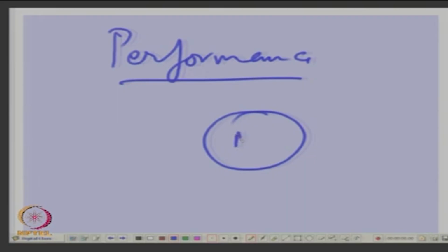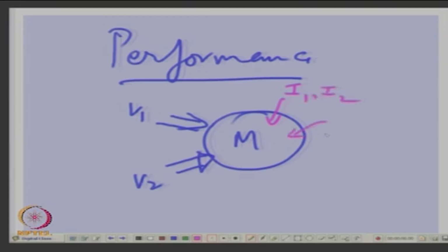because your motor will now be supplied with V1 and also with V2, is it not? What it means is you are supplying both V1 and V2, and then it will result in I1, I2 and it will result in T1, T2, which you can estimate for the given V1, V2 at a given speed. Is it okay? So, the net torque will be T1 minus T2 and the current would be I1 plus I2, the cumulative effect, the sum of these two; I0 is 0. So, you can estimate the steady state performance of a 3-phase motor with single phase supply with the given capacitance and speed. Okay.